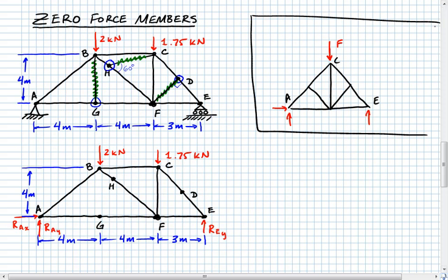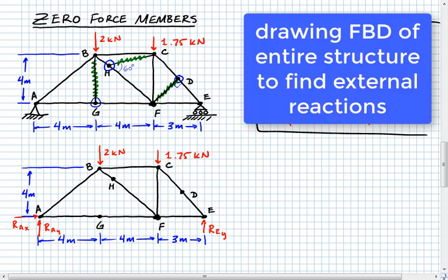All right, what I want to do now is we're going to go down here and notice that I have actually erased those members when I went down here and made a free body diagram out of the physical scenario that I started out with. All right, I've erased member BG, member DF, and member CH. All those have been erased now, and they're gone. What we can actually do here is, furthermore, we can just kind of erase those letters even, because we don't really care that there were ever joints there. It doesn't change how this truss gets analyzed.